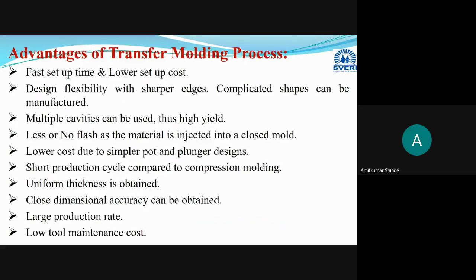So these are some advantages I have collected in this slide. What is the advantage? You can do the setup in very less time. Setup time is very less, and setup cost is also very less. Then design flexibility is there, which is an advantage over the compression molding process.